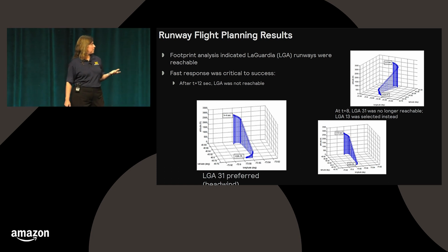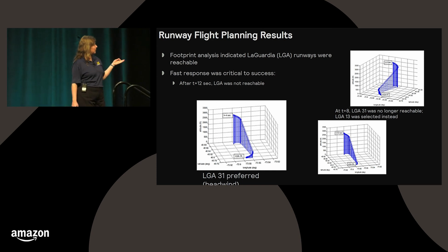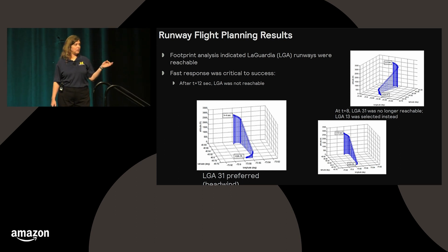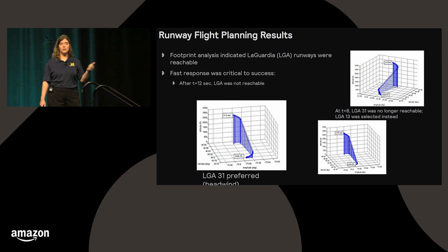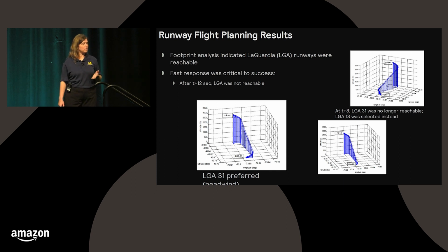It would have returned 3 possible flight plans, all 3 of them going to different runways at LaGuardia. And this turned out to be a pretty fascinating study, because what you find is that if you immediately begin the turn back, you have your choice of 3 runways. And all that was being used here was a geometric flight planner. There was no machine learning. There was no computationally complex search. It was all about turning and going using simple geometry. So this is something that could be certified, and should be available on every aircraft today, yet it's not.